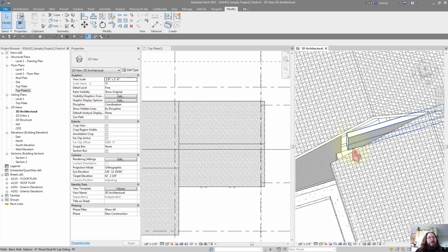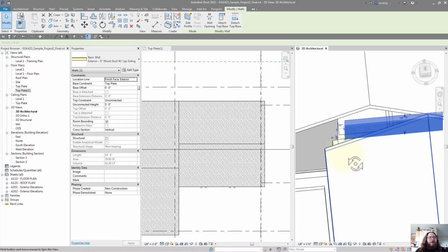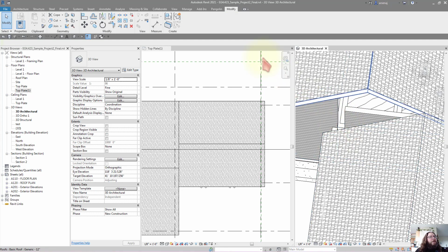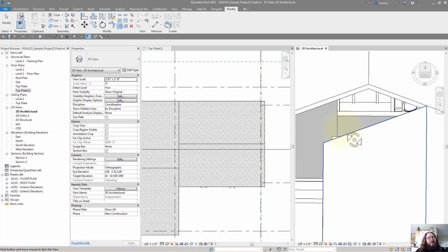Going to trim this wall, or extend this wall to this wall by going to Modify tab and picking this Trim Extend. I'll pick the Trim Extend, select the end of this wall, so I'll hover over the wall until I get the end and extend that wall to there.